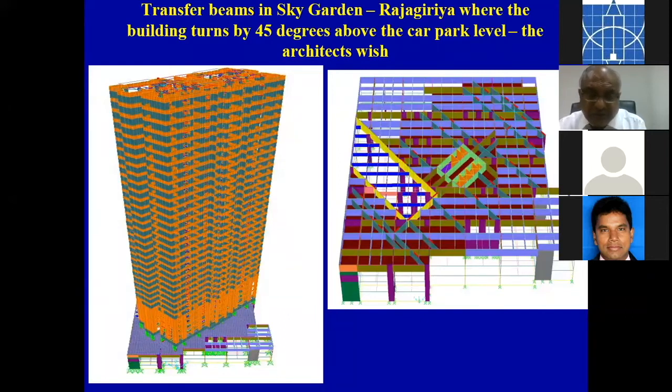So if you are not going to do any calculation for this particular aspect, how are you going to deal with it? Again, you will have a simple rule. What is the simple rule? Calculate the bending moment on the transfer plate from a model like this. Then calculate the dead load bending moment, and increase the dead load bending moment by 50%. Then you keep on adding all the bending moments for live loads, finishes, services, all will be added. Then you will find the final bending moment has increased by about 15% or 20%. And you will do the design for that particular bending moment. And then you can be a little more generous by adding a few more reinforcement bars.